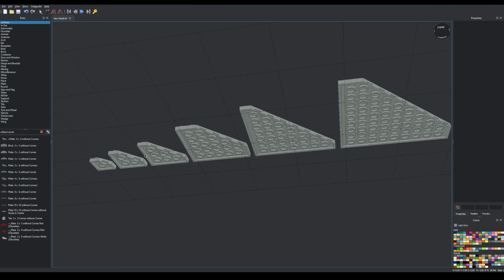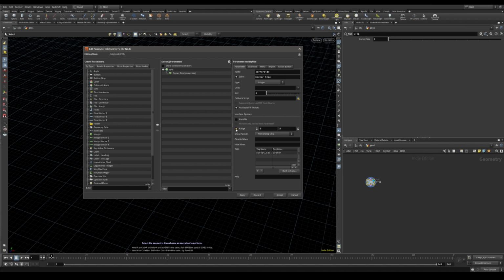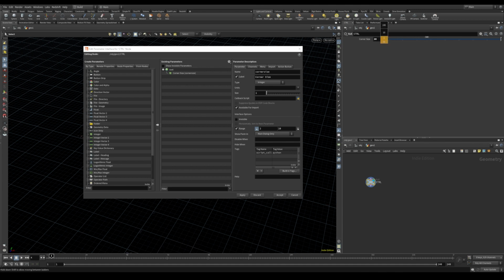And we know that our pieces will go from 2 to 10. So we can already set the slider for it by enabling the range from 2 to 10, and we can lock with this button. Basically, let's apply it for a second. You can see that we have the lock on the 2 and not on the 10. So the slider is actually from 2 to 10, but on the 2 we have the lock, so you can't even go lower with the mouse wheel. Instead, on the 10 we didn't put the lock, so with the mouse wheel we can go over the value.